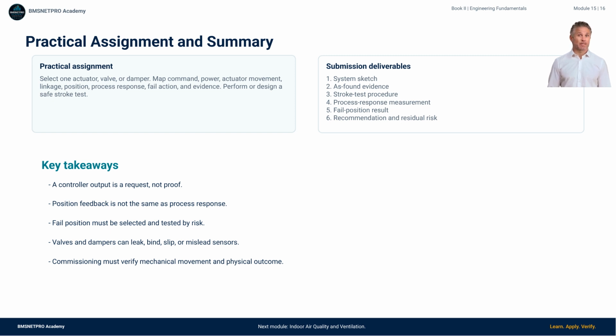The module takeaway is simple. A controller output is only a request. A professional verifies mechanical movement, process response, fail behavior, and residual risk before closing the issue. Next, the course moves into indoor air quality and ventilation.